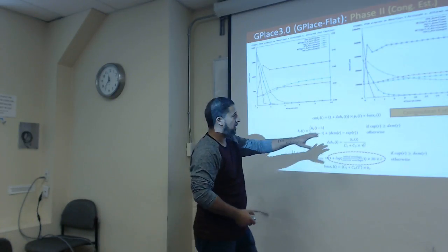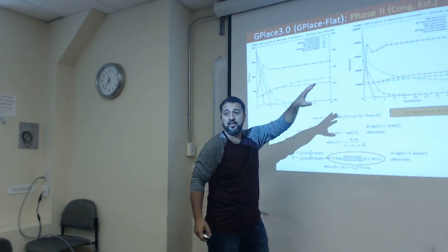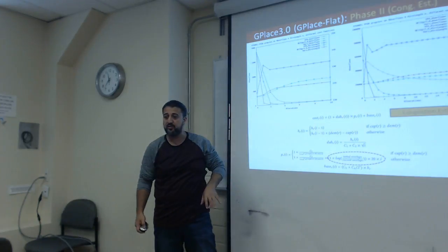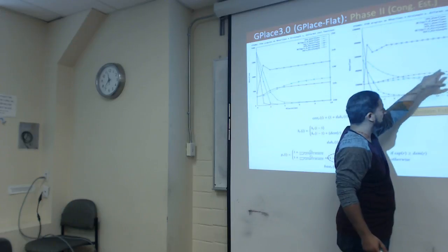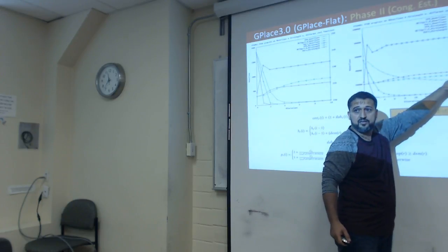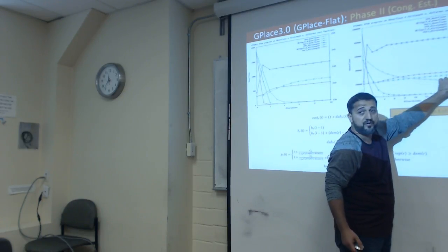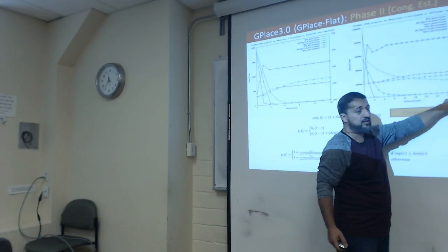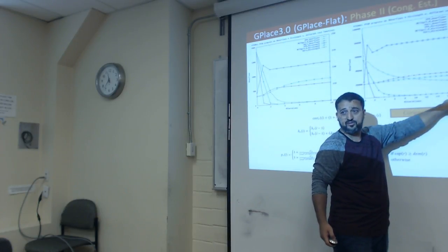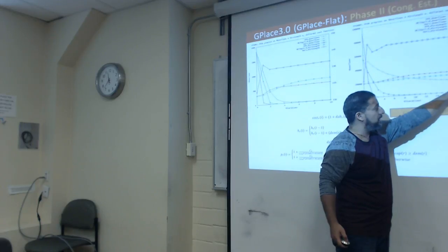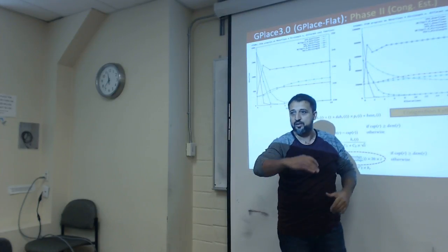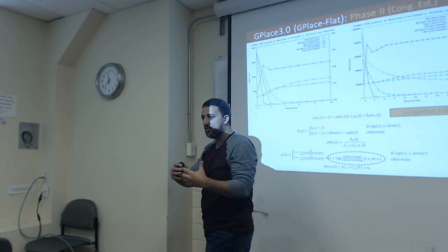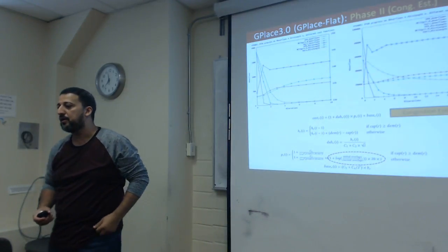Also here, for a highly congested benchmark that has a 0.8 Rent exponent, you see our wire length compared to the ASIC cost is a little bit higher, but we're able to get rid of most of the overflows, while the ASIC global router cost function is stuck somewhere and is not able to get rid of the overflows.